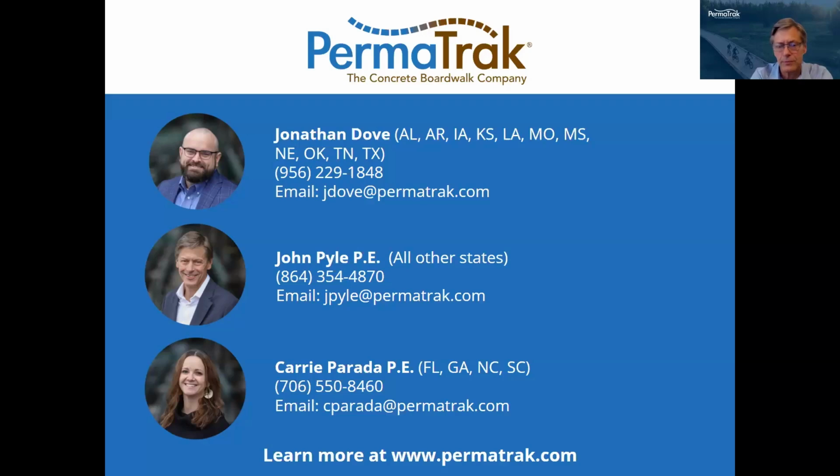Wind loading, as Jason shared in that wind map, you'll have a higher wind design load to be considered in a coastal environment. But for the issue of wave impact, there's really not a good way that we've seen to design a structure to withstand a hurricane-driven flood surge. It's just not very feasible.